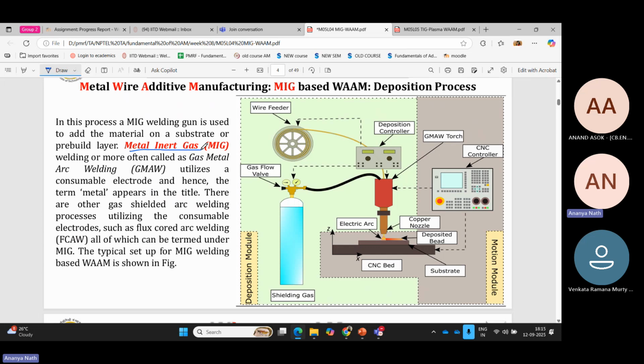My wire is fed from outside. That's why we make the substrate positive. Now the substrate will get heated, because there will be high heat. We need some dilution in the build plate. So the build plate is now getting more heat, so the upper surface of the build plate will get the heat and get melted from the top surface, which is needed in this process to get the dilution between the deposited bead and the build plate.